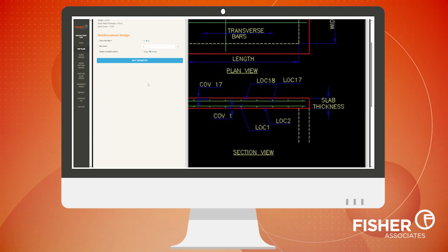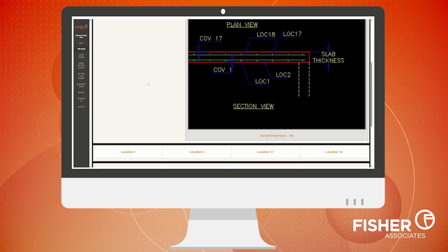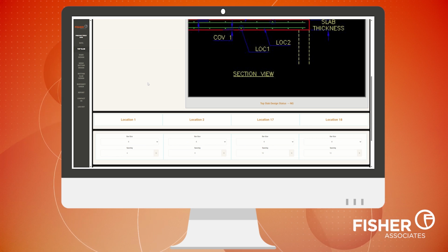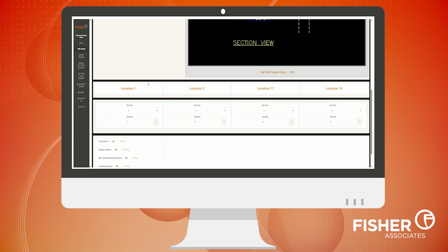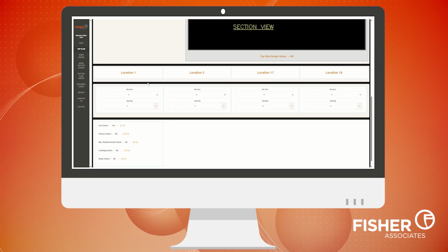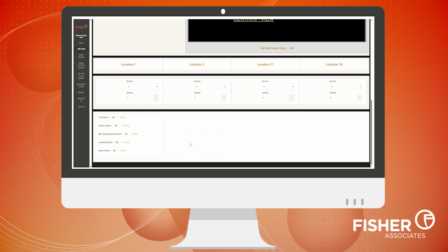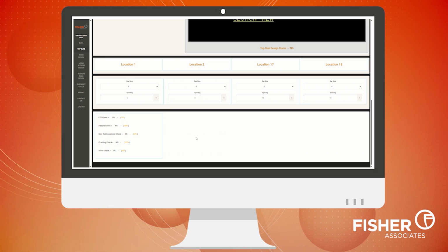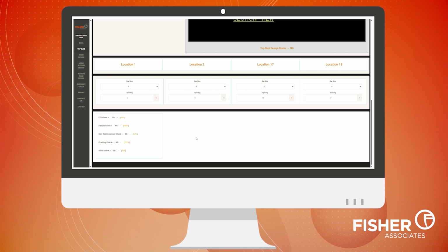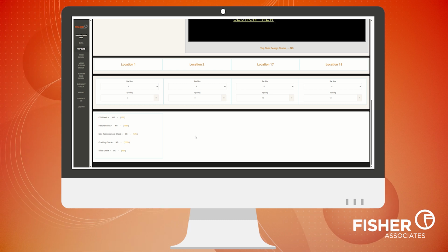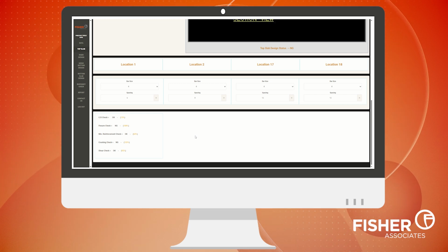Once the design is complete, the system will display whether your component passes or fails, as indicated on the plan. In this demo, you'll notice the top slab design status shows no, meaning the design has failed. To troubleshoot, scroll down to identify the issues that need attention. For the items that do not need to be addressed, you will see an OK next to it. For the items that do need attention, you will see a no next to it. For this demo, you will see a no by both the flexure check and cracking check.